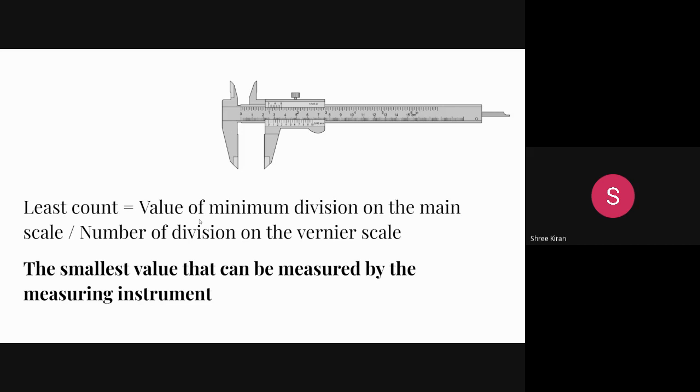For that, a thermometer is calibrated by measurements at a series of temperature fixed points, like freezing points, melting points, triple points, or vapor pressure points of pure metals. By this method, we insert the thermometer in a fixed point cell, which provides a desired temperature. We should already know the temperature, like boiling of water at 100 degrees. So we can insert the thermometer and check whether the value is correct or not.